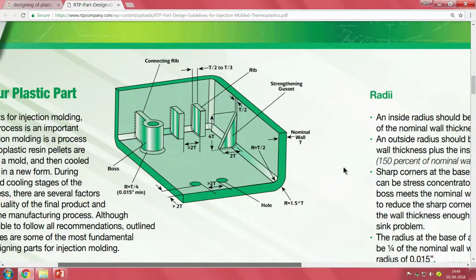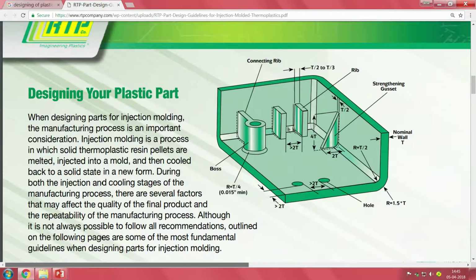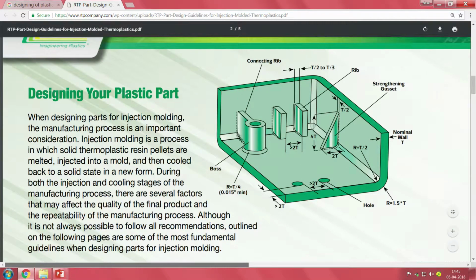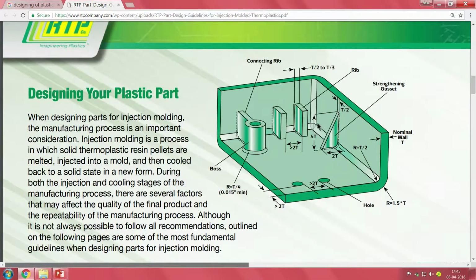several things happen. One of them is there is a tendency for it to turn a little cold, but those items are kept very much under control, and when you want to release it out of the mold, you end up having to provide a draft. Draft means a small taper such that it falls out easily, and you see all these names that are written here saying this is a rib so that something can be held strong.